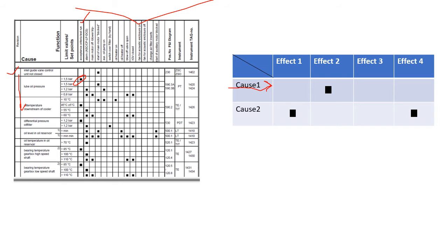And cause and effect is very important because based on this cause and effect, the logics of the safety PLCs are built. So if there is any error in the cause and effect, the same error is going to be reflected in the logics, and as a result our system will be faulty, and it will generate some false response, or there will be no response. That is a very dangerous situation. So that's why we should take utmost care while preparing the cause and effect diagram.